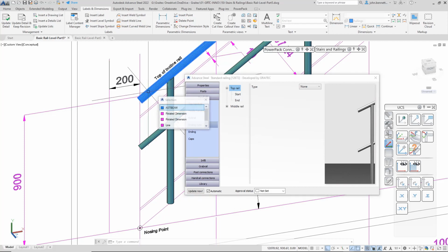So that's this element of the railing itself, and we're actually going to do it at the very top level, not at the branch level. So if you were to go down into the start or the end, you can actually change this individually within those branches of the tree. But we're remaining at the top level to start off with, and we're just going to come into this drop down dialog here, and we're going to select loop.